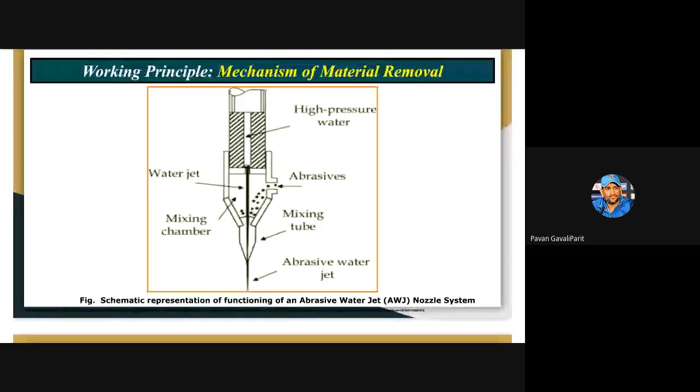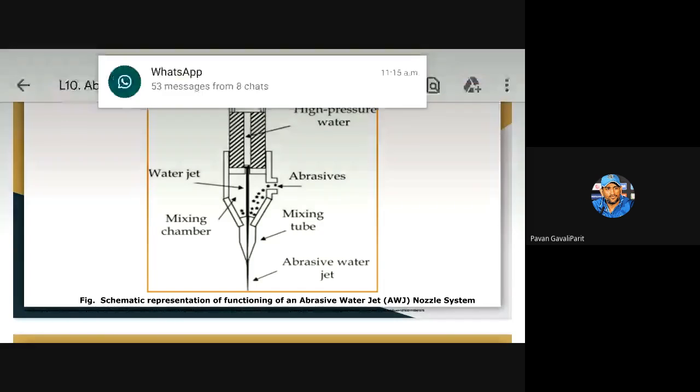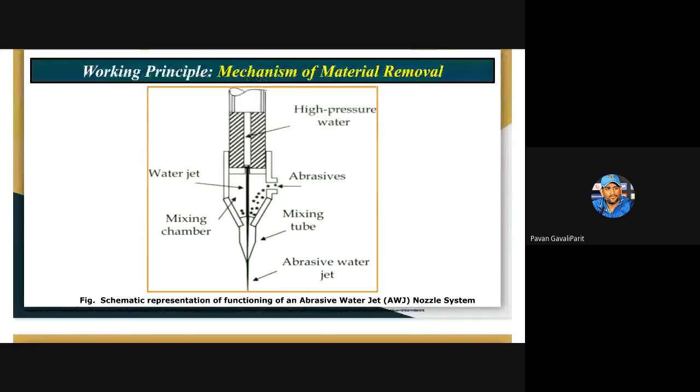A rapid rise in the abrasive velocity occurs in this mixing chamber. The abrasive particles coming out of the port will mix with this high pressure water jet.